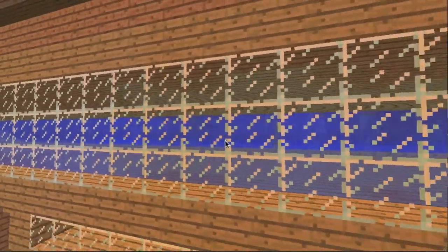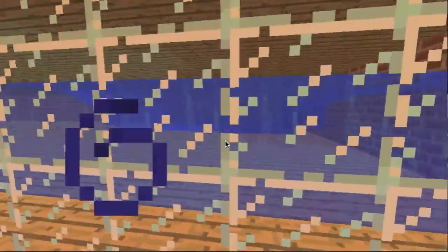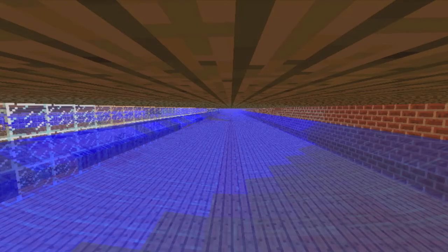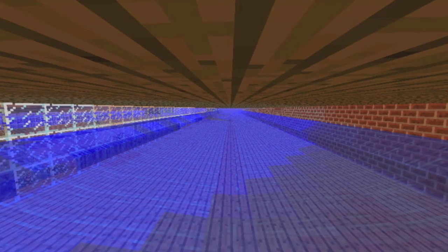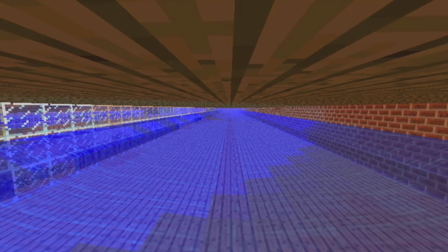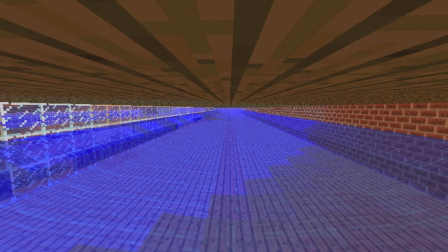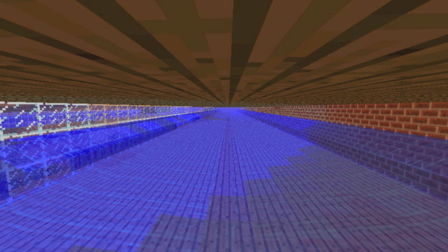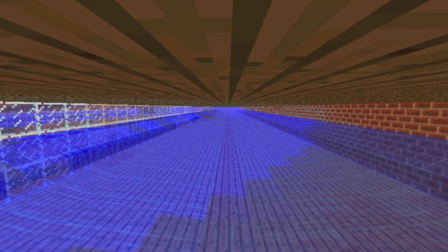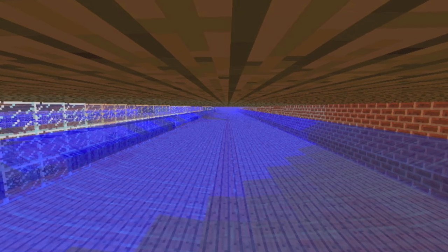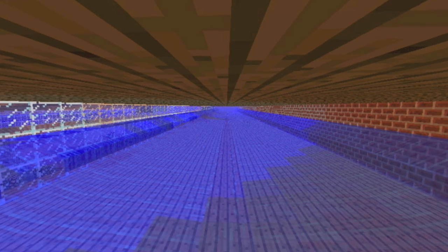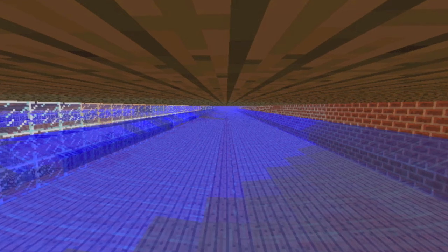Also, the rainwater tanks should include a solid, secure cover, a coarse inlet filter, which we will later talk about, an overflow pipe, a manhole, a sump and drain to facilitate feeding, and an extraction system that does not contaminate the water. All of these facilitate the process of storing and keeping the water clean. Of course, the amount of water you obtain will depend on the amount of rainfall. In the school's case, this will not be a problem, as in Holland it's always raining.